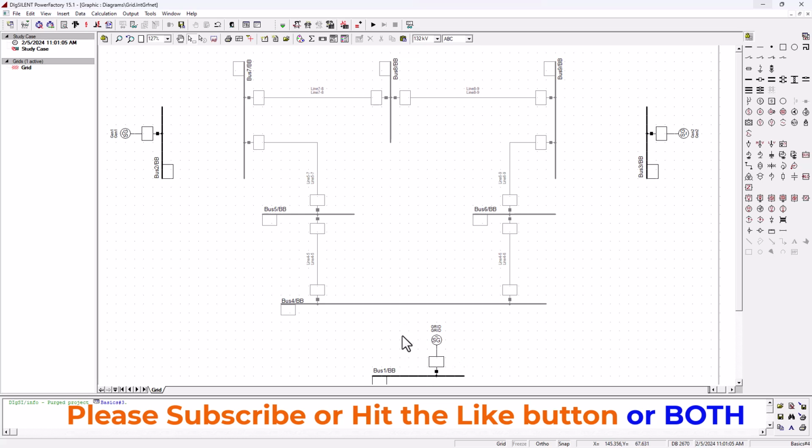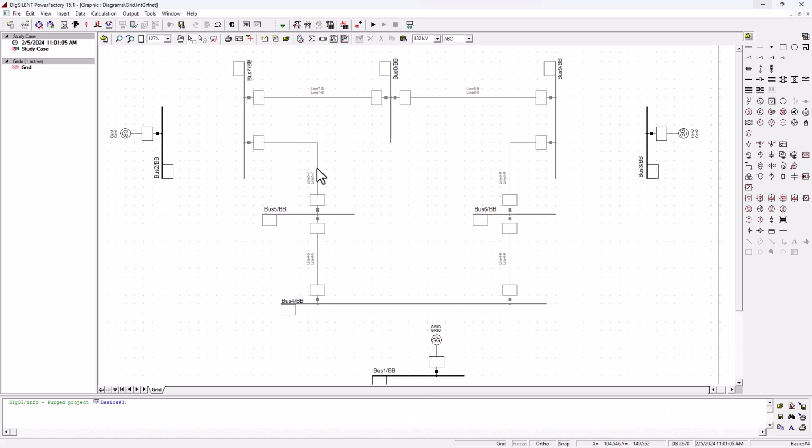What we need is transformers, because we want to get power to some remote location. We cannot transmit at 13.8 kilovolt without stepping it up, because that means we have to transmit at a higher current to get the whole MVA through. If we transmit at a higher current, remember the losses.